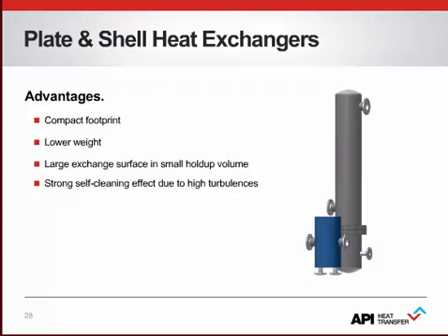Very compact design, and therefore it's typically with lower weight and with larger surface area in a smaller hold-up volume. The self-cleaning effect due to high turbulences between the plates allows it to be used also for dirty applications.